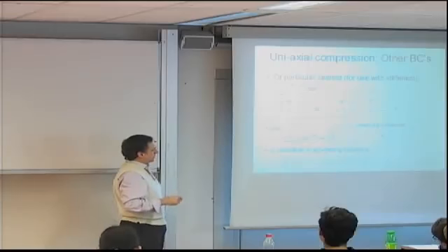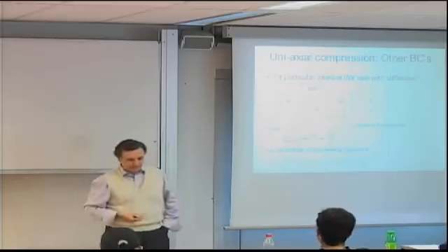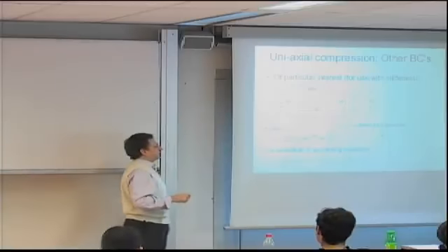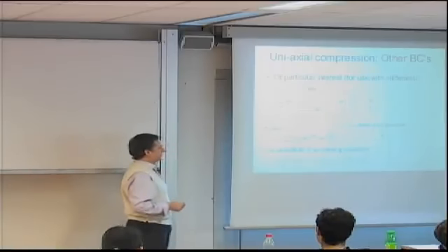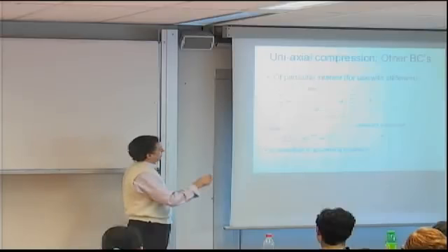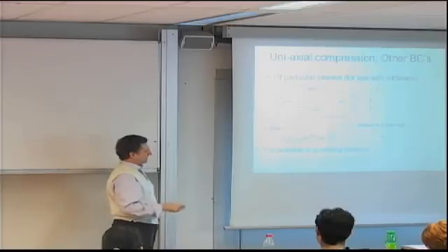So going back to what we started with for the simply supported case, we use the same expression, but now we throw in a lambda here, which is a pure number, a real number. And we do that, this is an approximation. We do that because depending on the value of lambda, we can get different boundary conditions along this edge. The equation we still need to solve is the exact same one as before.